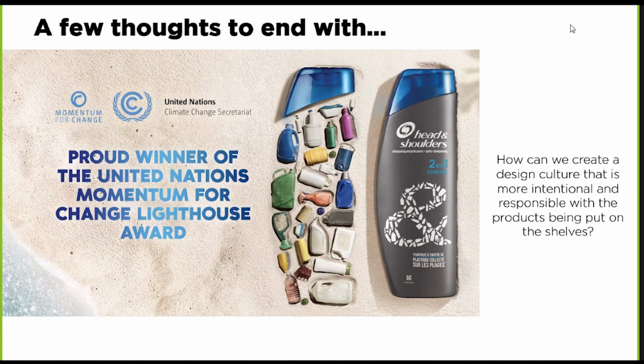It actually breaks the plastic polymers down into shorter and shorter pieces, and it becomes very brittle and powdery, and it just breaks and falls apart. And the recycling process, melting that down, does not magically make those polymers grow again in length. And so to make this product on the right, they had to add a huge percentage of new plastics, and there's only a small amount of the ocean plastics in there.